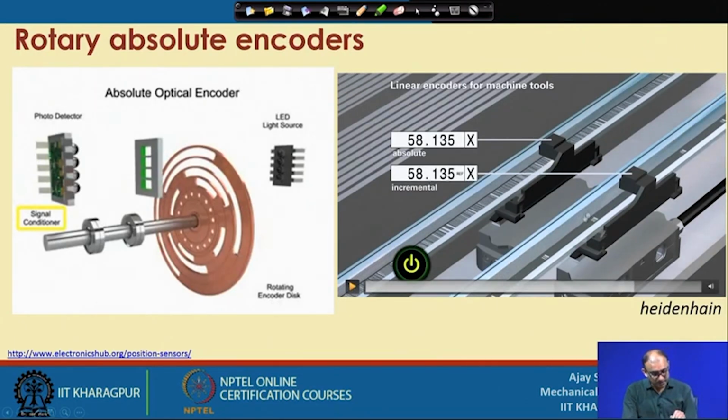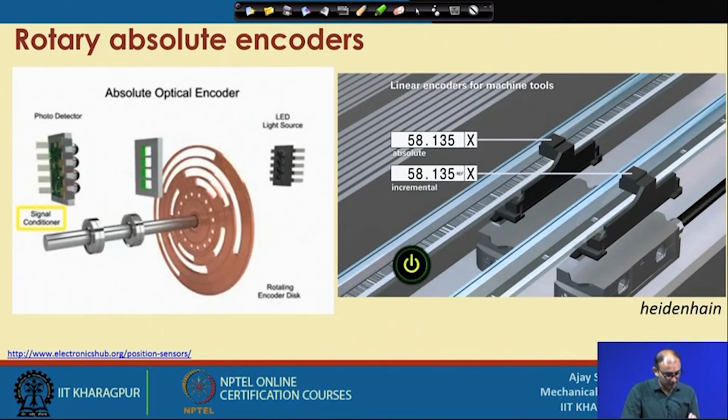So, now you can understand how both encoders work, the absolute encoder and the incremental encoder. We have taken the example of the linear encoder, but this is the same for the rotary encoder also. When you are using an incremental encoder, you have to go to the reference position first to get the exact position, but in the case of an absolute encoder, whatever the situation, it creates a unique binary code, and depending on that you get the position. So, there is no issue with that part.